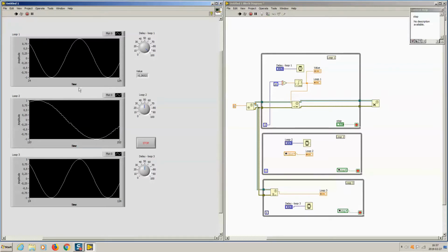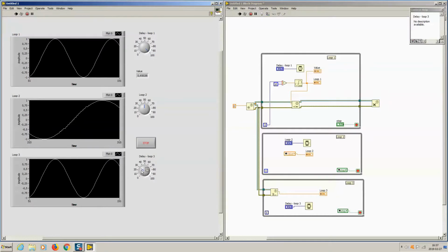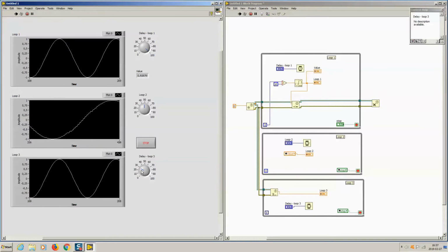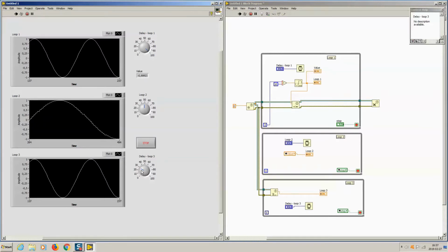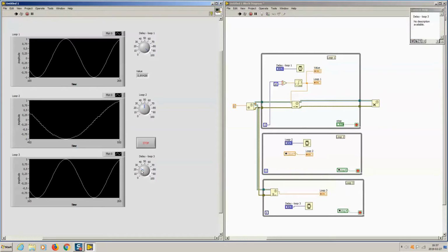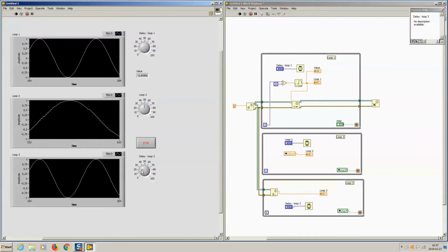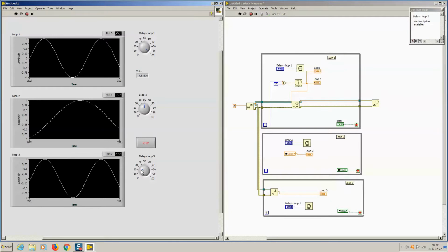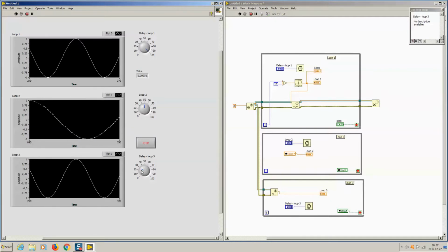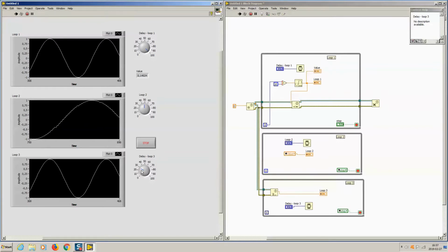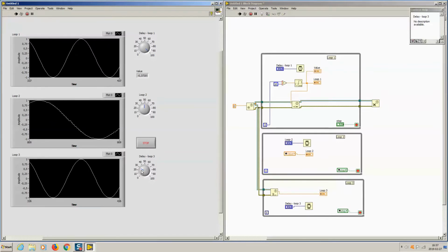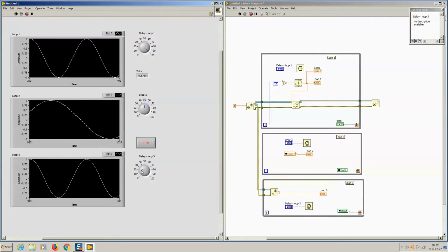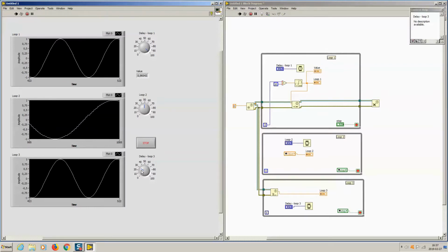Due to the possibility of synchronizing several loops using the notifier, it has been applied in the master-slave design pattern. The mentioned pattern is used when we need to perform some actions in parallel and with different frequencies. The master-slave pattern is built from only one master loop and one or more slave loops. The master loop controls the operation of the slave loops and communicates with them through a messaging architecture such as the notifier. Each loop is a separate task. Therefore, by separating tasks into different slave loops, we make the application more modular.